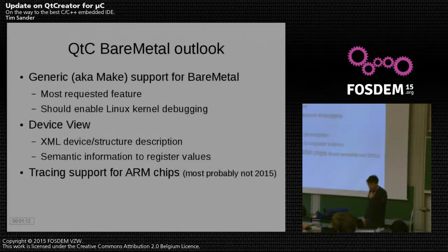And with generic support, it should also be possible to use QtCreator for debugging the kernel, which would be quite neat, I think, because if you're doing some driver development, you could then use it, for example, with a BeagleBone. The white version had an onboard debugger, for example, and then you could directly use it for debugging the Linux kernel.